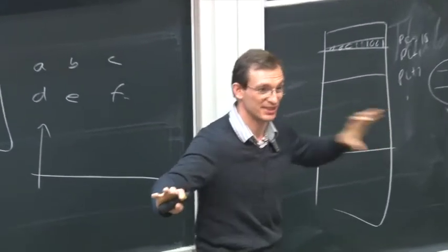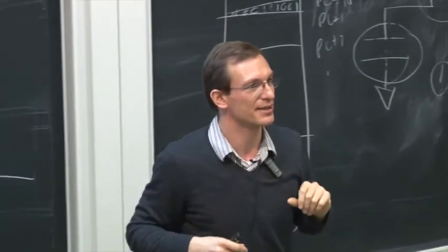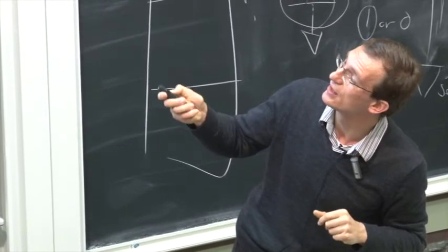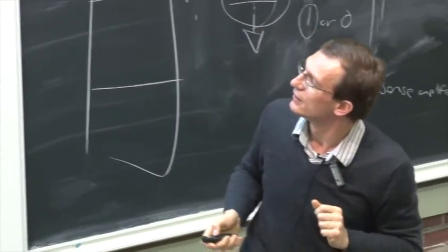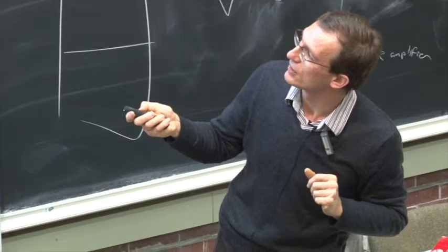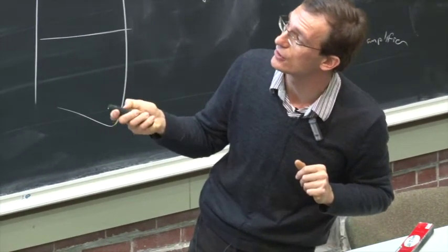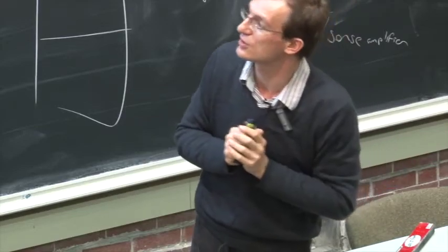Instruction and data caches are separate. You could argue that that contradicts the von Neumann model. But underneath, we're not exposing any of this to the programmer. Yeah, I think I've already told you this. What happens underneath that is not consistent with the von Neumann model is not exposed to the software. That is the difference between ISA and microarchitecture.